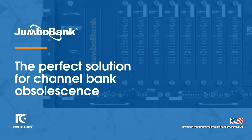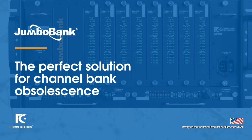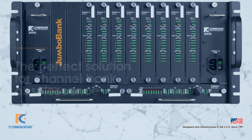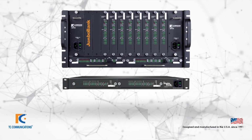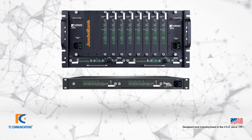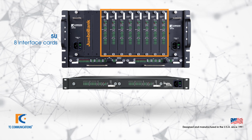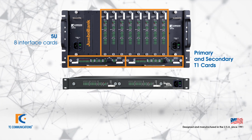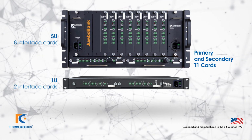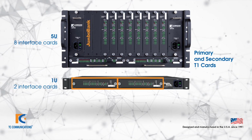Let's say you would rather replace the channel banks you have with a modern alternative, but still want to use your existing network. We have 2 main options. For complete channel bank solutions, we would use the JumboBank. There is a 5U rack and a 1U rack option. Our 5U rack can hold up to 8 interface cards and hold 2 fully redundant T1 cards for primary and secondary redundancy, and the 1U can hold 2 interface cards.